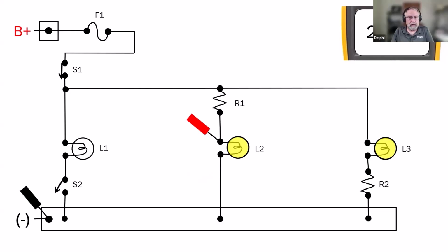So now we've got to narrow it down. Okay, so now we know, it's that law of halves, right? We've cut it in half. Lower half is fine. Let's go to the upper half and figure out where specifically this problem is taking place. So we start doing voltage drop measurements across things like your fuse holder. Our fuse holder in this case has a voltage drop of 6.5 millivolts. Is that unacceptable? No, it's just fine. There's no problem there at all. Is there resistance there? Yes. Is it unacceptable? Not by any stretch.